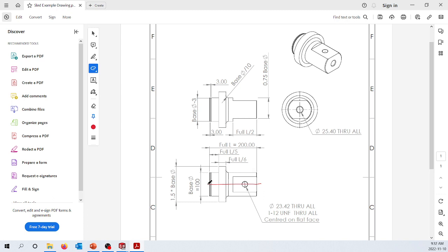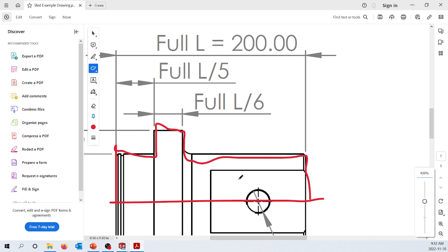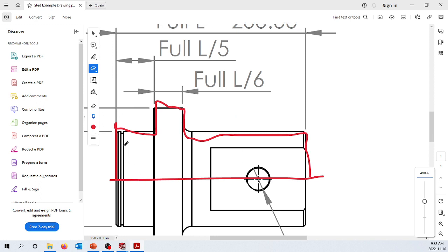So what I am going to draw is this shape. I'm going to skip a couple of features intentionally. Should have zoomed in further before. I could draw this groove in on my first pass, but I want to do that as a second one, just to show you how tools work. I am going to include this fillet. I'm not going to include the chamfers. So I'm really just drawing the silhouette of half of this thing, and I'm going to rotate it along its central axis, and that will make the full part.